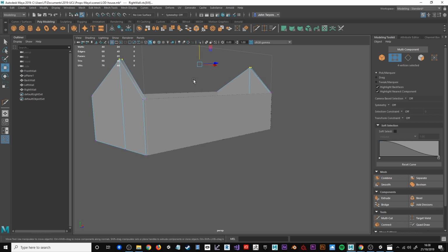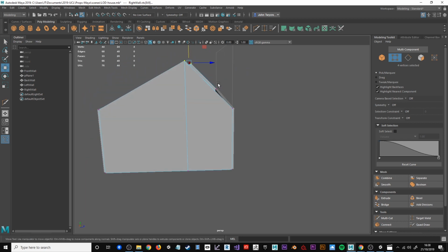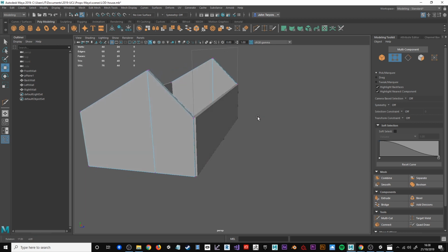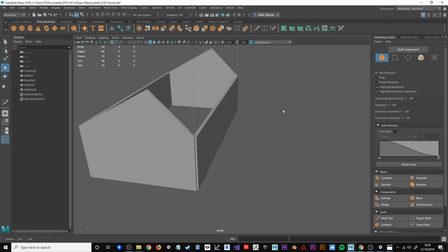Now it is slightly forward on the building. That's how I designed it. I want to have a sort of long runoff, and I designed it to have a specifically sloping frontage there as well. So once I've done that, I can go back to object mode with those, and those are done. I'll save it again as I'm going forward.